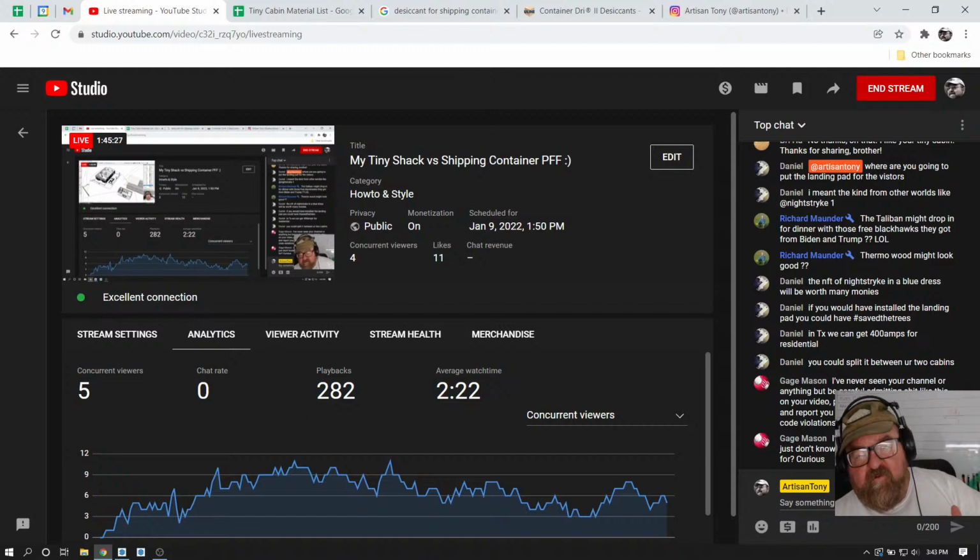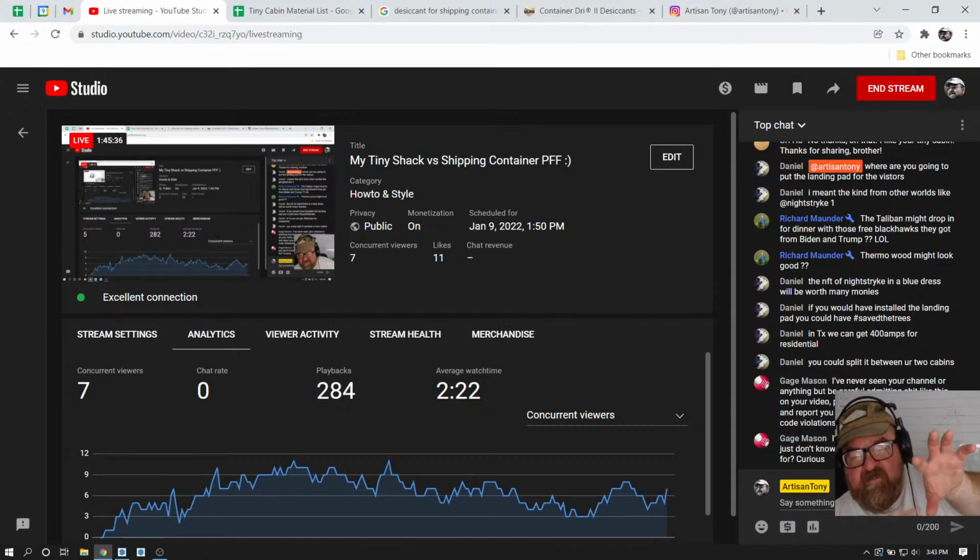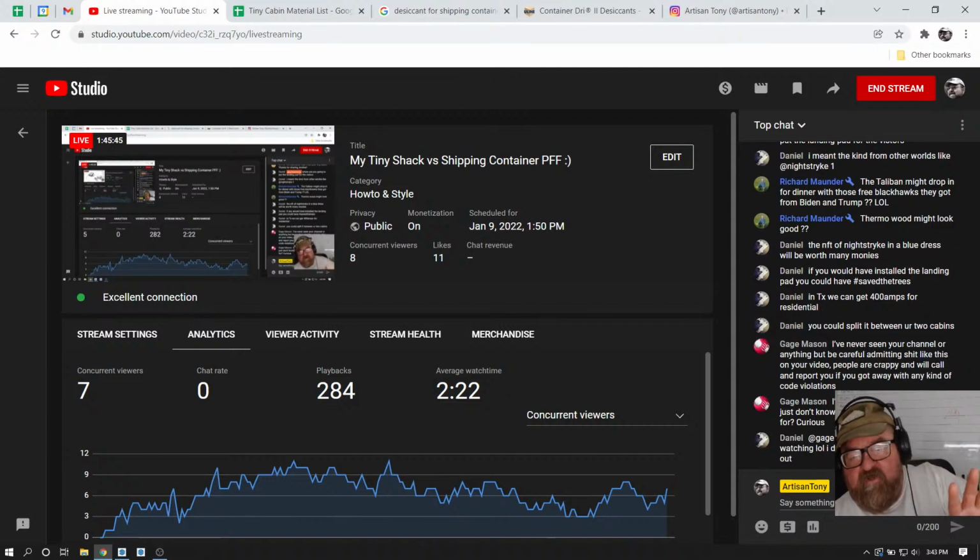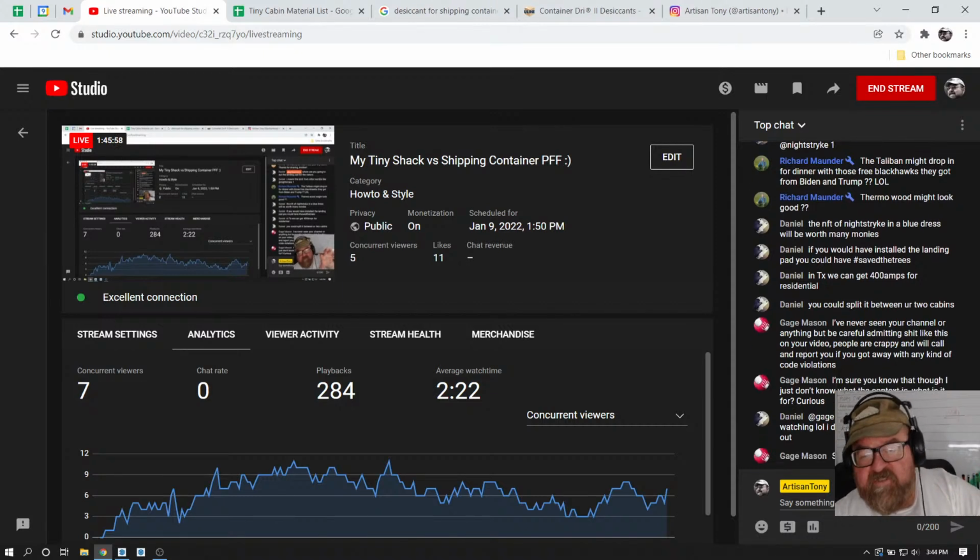Most people put up RV poles with only like 60 amp panels. It's an RV pole. You can buy them. They're a meter base, and then there's a place for like a 50 amp or 30 amp plug for the RV, and then maybe another breaker or so for the GFCIs. You have to have two GFCIs on the bottom of that panel. That's what an RV pole is. If you look it up, you'll see.